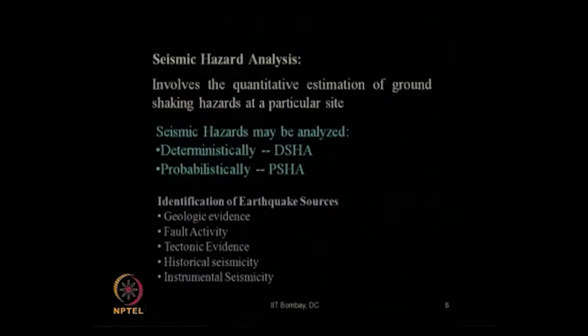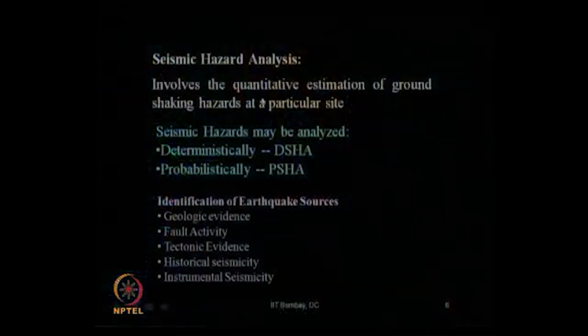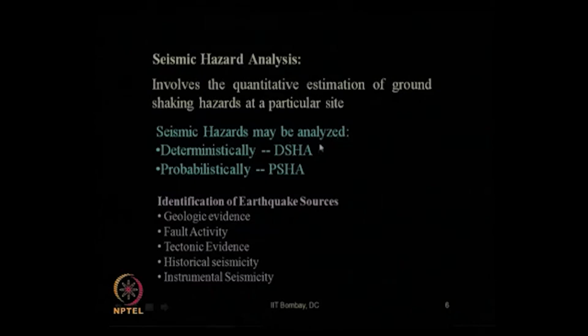So, the seismic hazard analysis involves the quantitative estimation of ground shaking hazards at a particular site, and it can be analyzed deterministically or probabilistically. These are the two ways through which seismic hazard can be analyzed, that is DSHA and PSHA. So, how do we go ahead further?